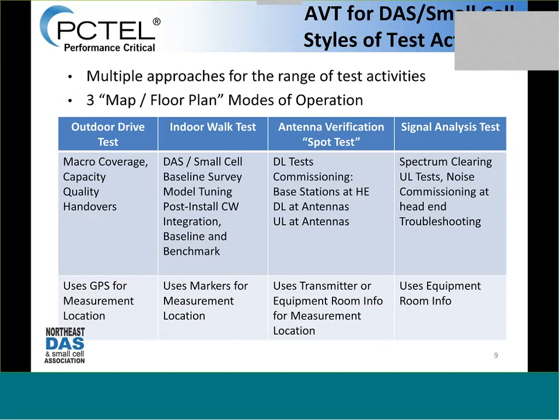And, of course, there you'll see, particularly as I've listed some things that are particular to the activities I just mentioned and how they apply to DAS and small cell systems. So, for instance, if you're doing a baseline survey, you're using a walk test tool. If you're collecting the data you need to do model tuning, yes, you're going to be walk testing. And certainly near the end, where you're doing an integration and a baseline benchmarking, you're often not just using scanners, but using test UEs as well and an integrated test tool.